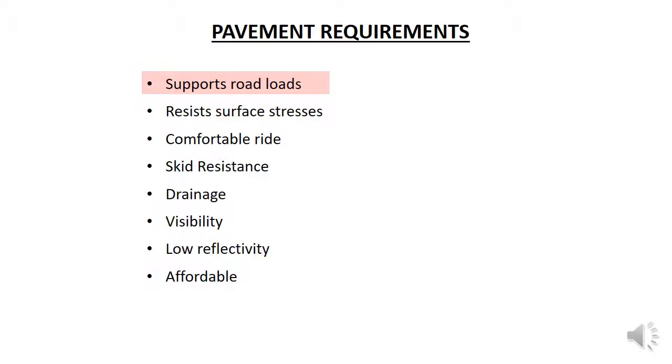One of the main requirements of the pavement is to support the traffic loads and reduce them down to levels that can be carried by the subgrade without deformation or failure. The pavement needs to support these traffic loads for long periods of time without breaking up. Specifically, the whole pavement needs to resist the normal stresses from the weight of traffic and the shear stresses from vehicles accelerating, braking and turning. The surfacing and base course surface in particular are especially prone to damage from traffic loadings and need to be designed to resist them.